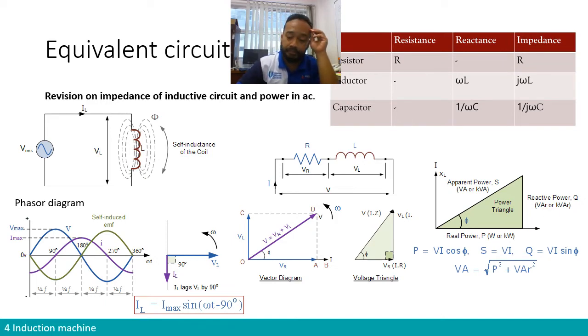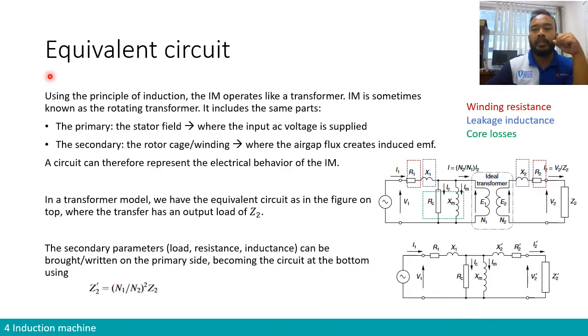by the stator. So by now you understand that the operating principle of an induction machine is relying on the principle of induced current. So in stator you have an AC current, and the rotor is basically a passive component. It's not supplied with electricity. It's just put in the middle, and the magnetic flux goes across it, and the variation of magnetic flux inside the rotor will create the induced current. So this principle of operation is exactly the same as what we have in a transformer.